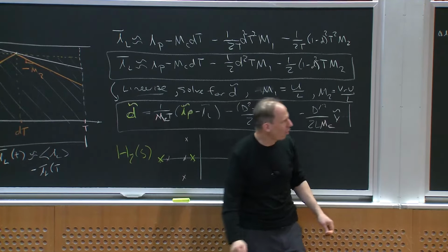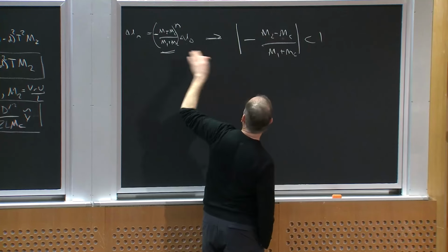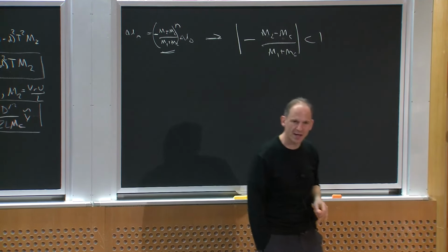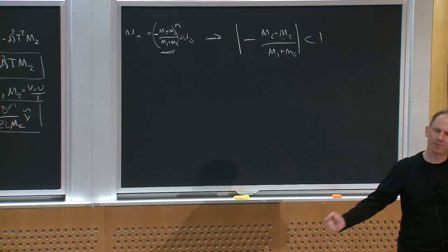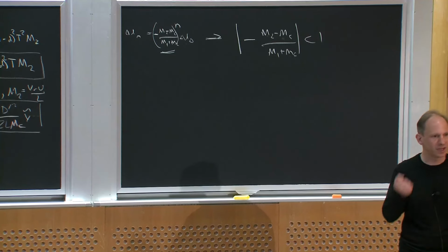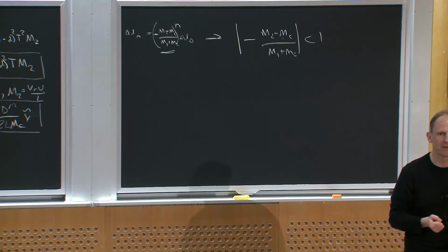I could also obviously make my compensating ramp slope depend upon M1 or M2 in some way. People don't usually go to that range. If you have your converter operating over a really wide range, maybe you start to play those games. But generally, you're just picking some slope and setting it with a resistor or something.